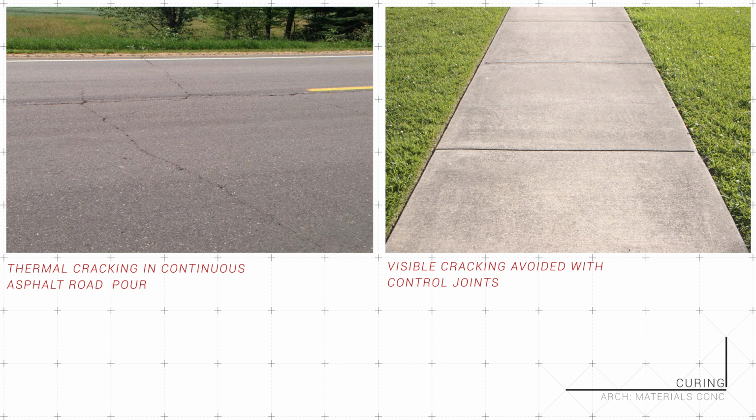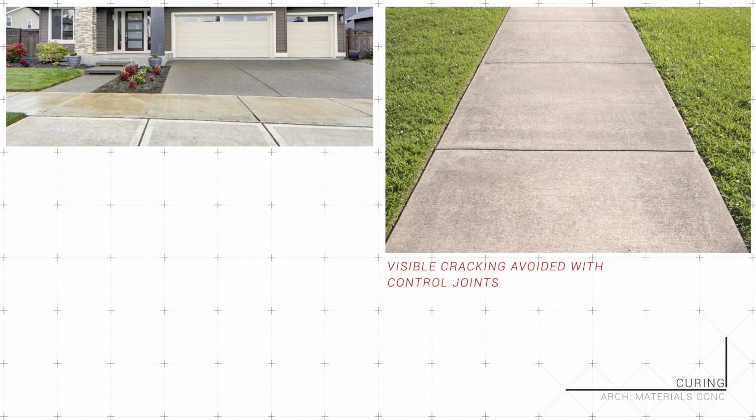Sidewalks hide this by concentrating the cracking inside the control joints, but this doesn't work when concrete expands and then abuts against something it could cause damage to. Like a sidewalk abutting up against a driveway, if a slab heats, expands, then crashes into its neighbor, there could be damage. More so if the case is a large civic project like road and bridge connections.